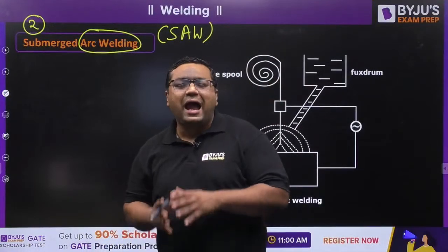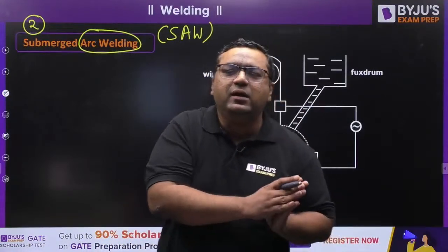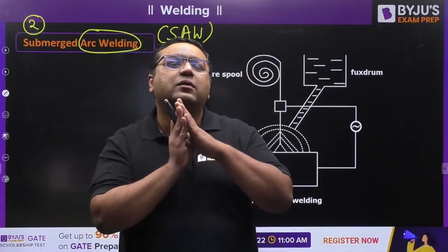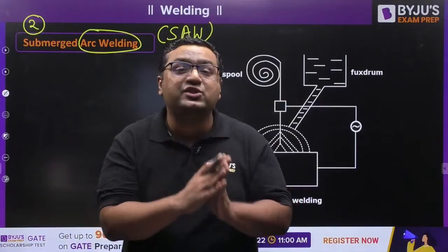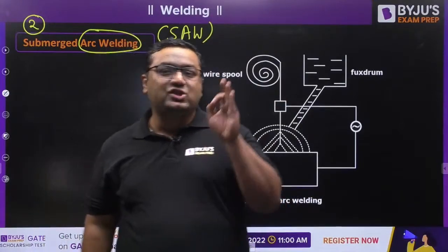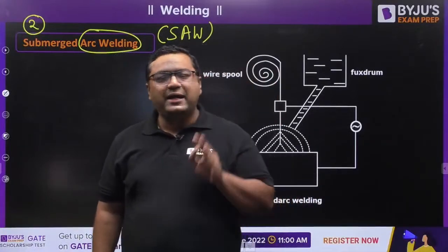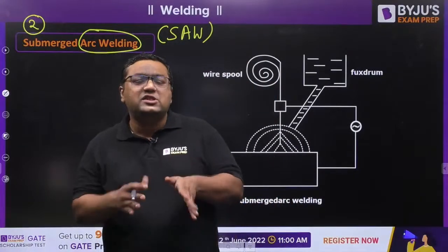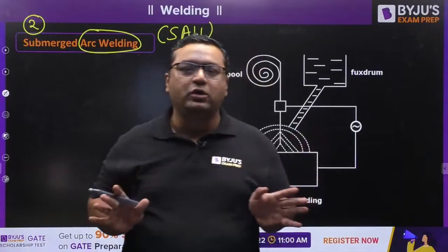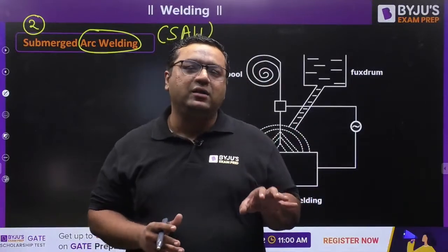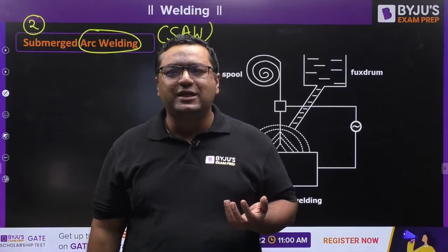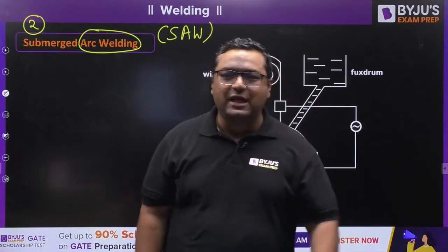So my dear, for applications like shipbuilding, pressure vessels and LPG cylinders, where there are chances of leakage, we want continuous welding, which shielded metal arc welding was not. Because of that, we wanted some advanced process which is going to be of continuous type.